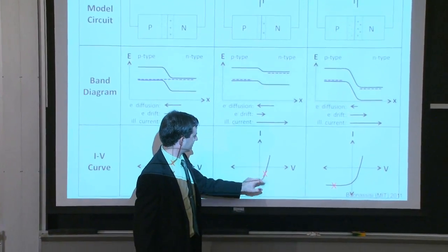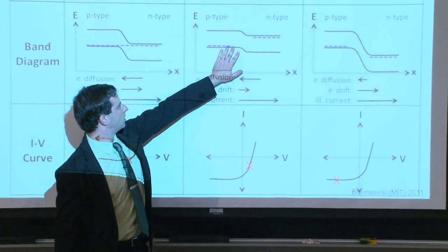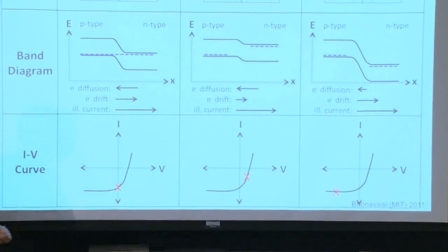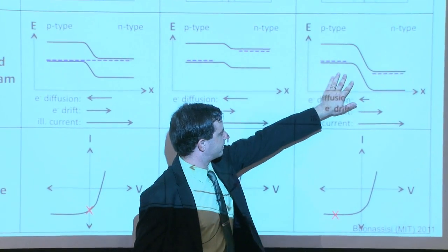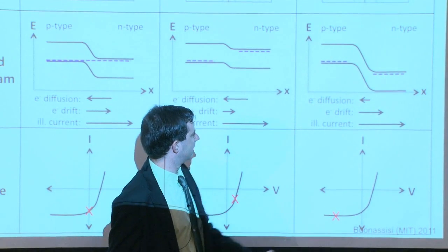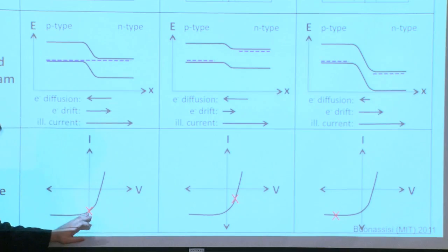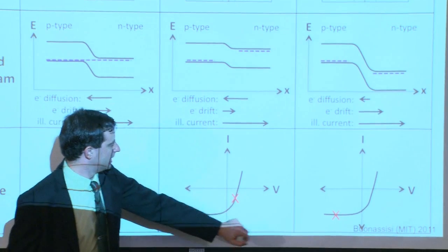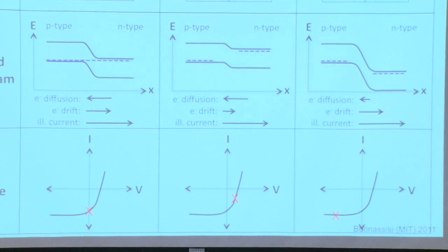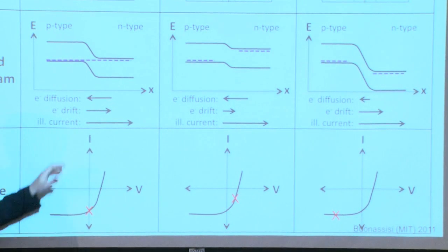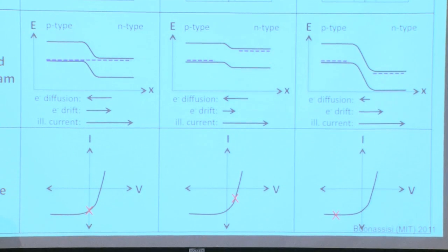We have our red X under forward bias conditions in the fourth quadrant, denoting that power would be flowing out of this solar cell device under these conditions. And now the bias is inverted. We have reverse bias conditions. And notice that the current still has the same sign. So the current is negative here, and negative here. So the net current is always flowing in the same direction in all cases, because we have this illumination current, because we have this generation of carriers inside of the material.